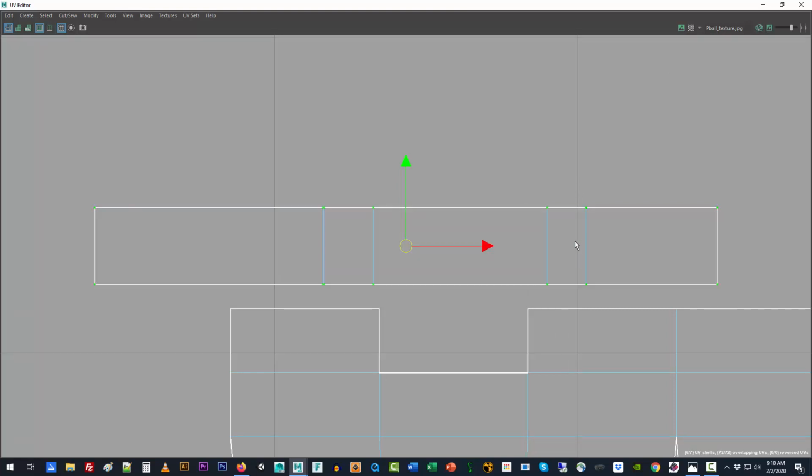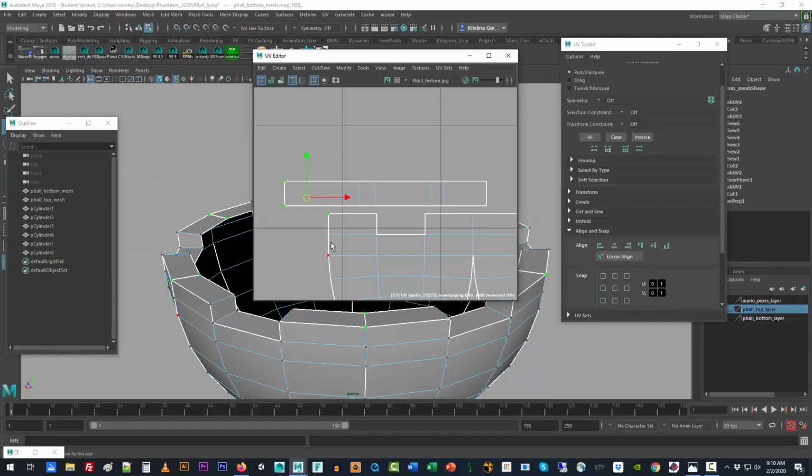So I'm going to grab the UVs, and again I'm grabbing them all at once, so all these different sections are on top of each other, and I'm going to use that trick of alignment to line them up right to this edge here of the orange slice by clicking this button, because the white edge is to the furthest right, which is where I want these to align. So click, that worked. And I'm going to align these over to the left because this is my template. This is what I want to match. This is what I want to modify.